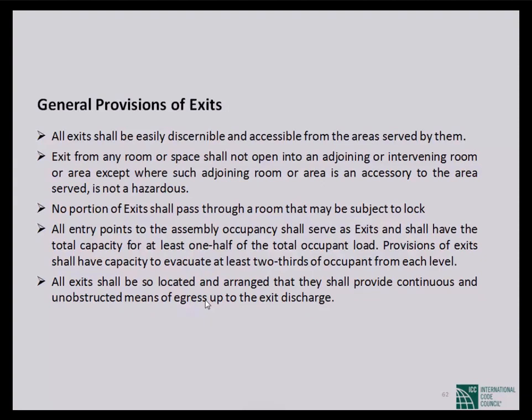Exit from any room or space shall not open into an adjoining or intervening room or area, except where the adjoining room or area is accessory to the area served and is not hazardous. In some buildings I have seen a fire stair, but to get to the fire stair you have to pass through the kitchen.